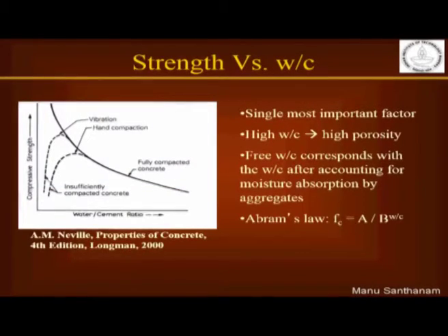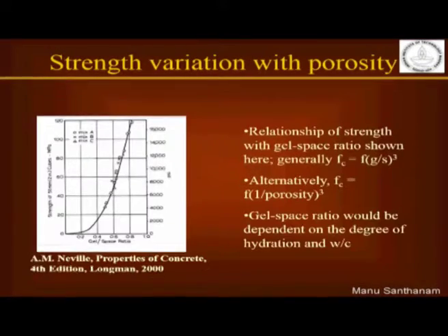And we looked at this simple relationship that people often prescribe for water cement ratio to strength, and this is qualified as the Abrams law. Unfortunately, this law is just an indication that compressive strength decreases with an increase in water to cement ratio. There is nothing universal about this. The other aspect was the fact that strength depends a lot on the porosity that is developed in the systems. The more porous your concrete, the less strong it's going to be.